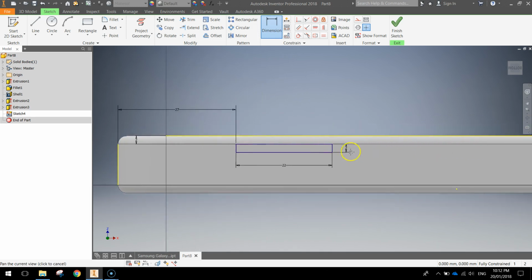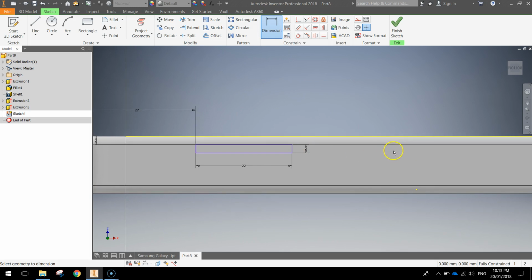We're going to draw a second button now that comes in a little bit further down, which is the Bixby button. Okay, it's like the Siri for the Samsung. So this one is going to start pretty much level with this button here. So on this line, okay, I'm just going to click on it and drag out. It needs to be 11 width and 2 for the height. So 11 mils width, 2 mils height. Press enter once you've got it.